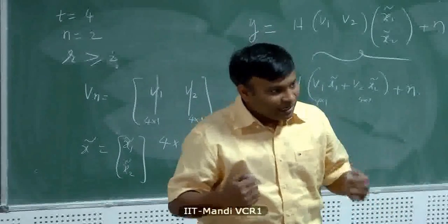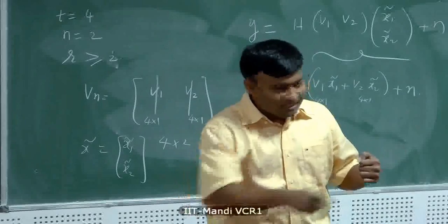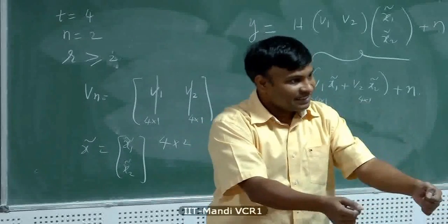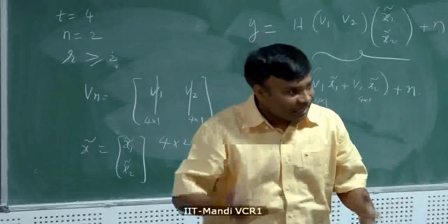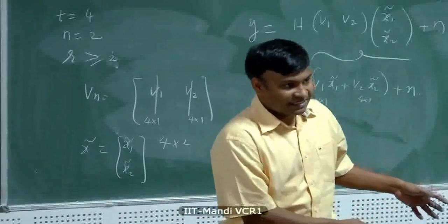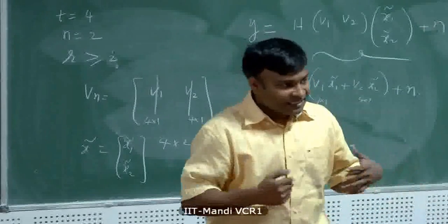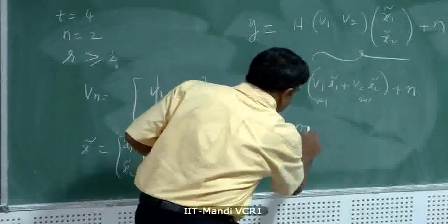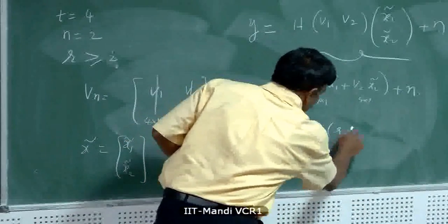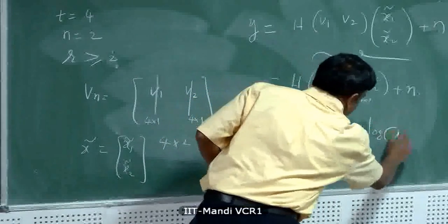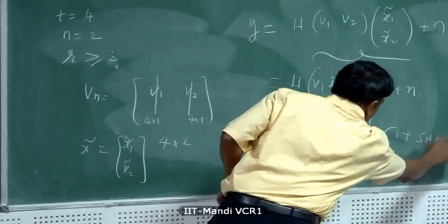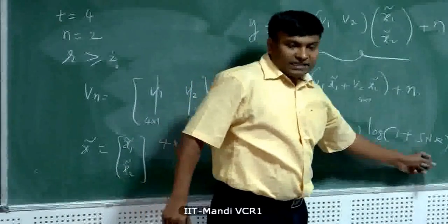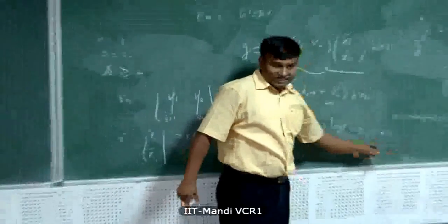That is, you should put multiple streams, find the eigenvalues of this big matrix, send multiple streams, and get spatial multiplexing gain, rather than shoot for the beamforming gain, which is the SNR improvement. So, in a minimum of R comma T, log of 1 plus SNR kind of formulation, it's futile to increase the array gain by improving the SNR.